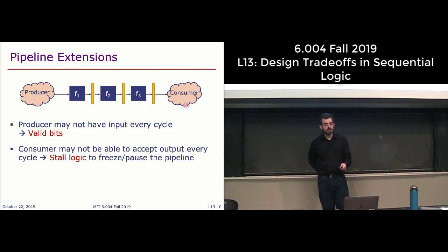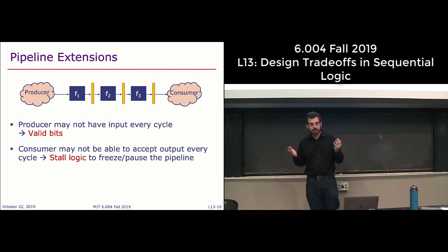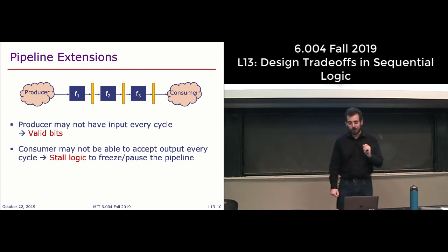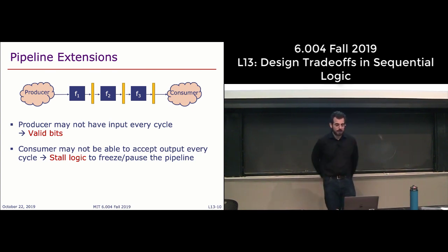Maybe this is some circuit that takes multiple cycles to compute, to process each output. Or maybe on average it takes 1.5 cycles, so many inputs take 1 cycle, but in some cases it takes 10 or 100 cycles. And this we will see: when you build processors, you'll see that this is precisely how memory behaves. We're going to be able to build a circuit that in the common case takes 1 cycle, but sometimes it's going to take 100.